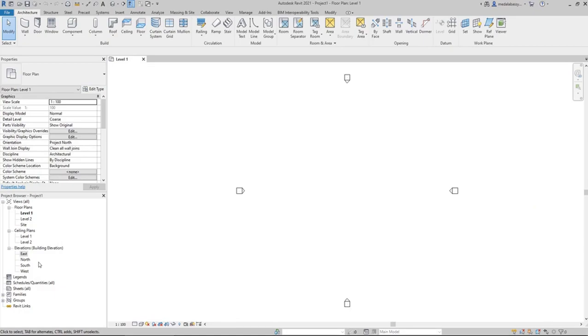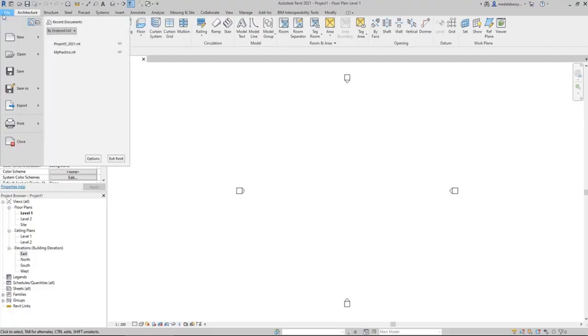So yeah, that's it. First thing, before you start actually getting into the modeling part, you should check the construction family template you're using. To check that, you can either do it for the first time while you're creating the project. There was a button at the right side. You can just browse to the family template you want, or you can just set it by default from here, to be used always when you create a new project.